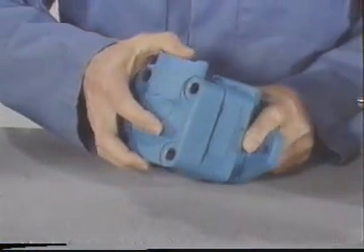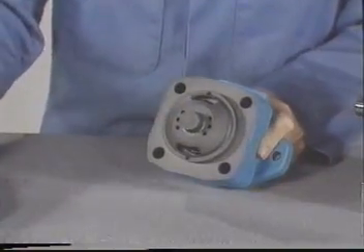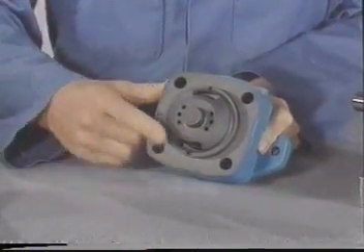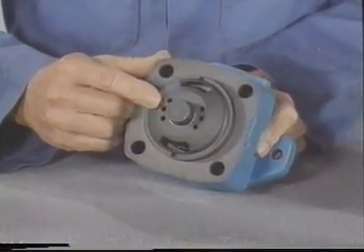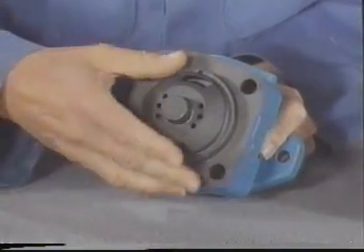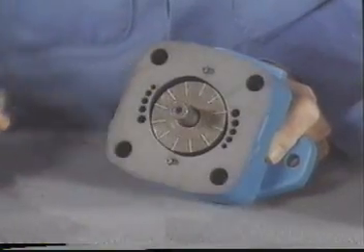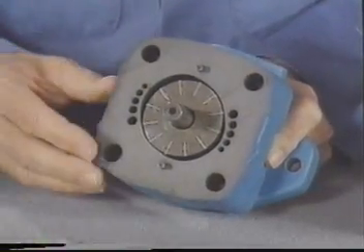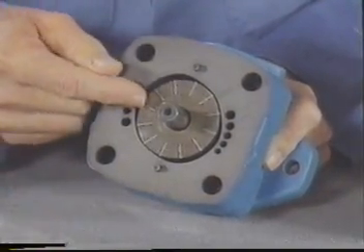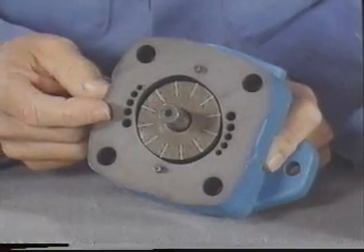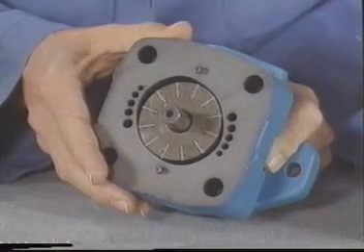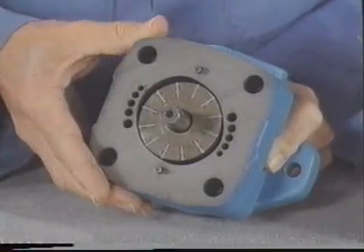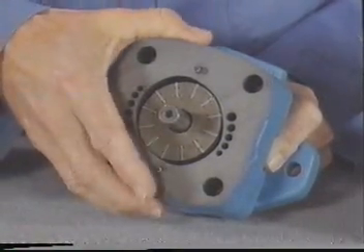By removing the cover, we can see the two pressure passages through the pressure plate, as well as the small holes which direct oil at outlet pressure to the underside of the vanes. With the pressure plate removed, we can see that the slots in the rotor are radial, and while it may be more difficult to see, the vane tips have a symmetrical radius. This means that neither are affected by drive shaft rotation.